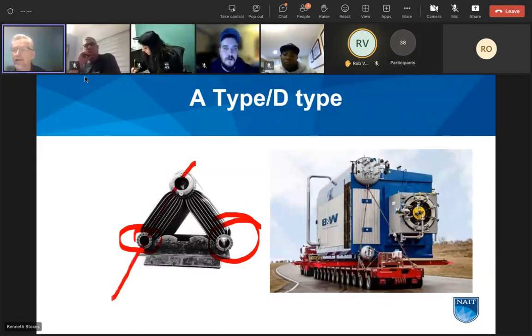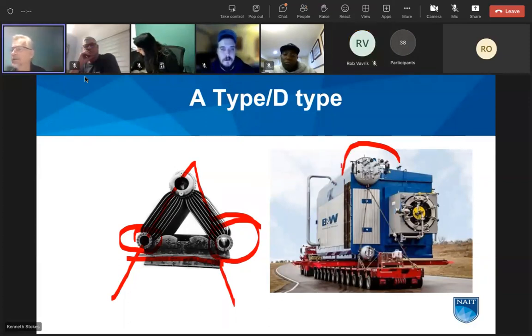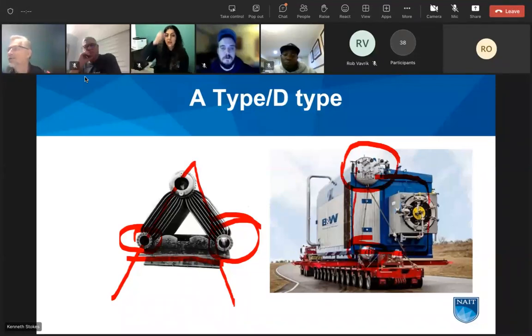So this one's called an A type. I like that one. It really does draw an A, right? Two mud drums at the bottom, one steam drum at the top. Over on the right here, we have a package boiler on a truck. And it's steam drum at the top, mud drum at the bottom. Bent tube style, so there's water walls surrounding this furnace. And there's the burner, and the furnace is inside. So try to keep it clear.